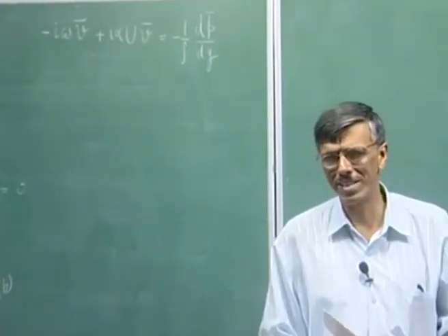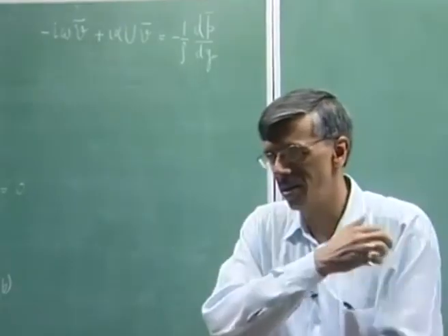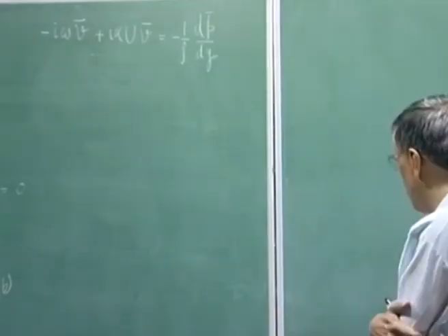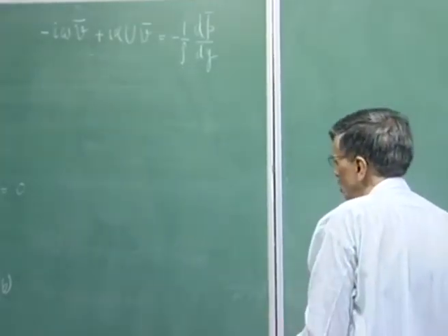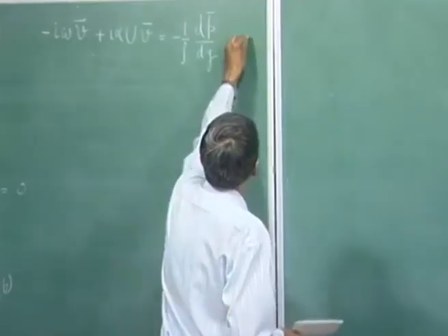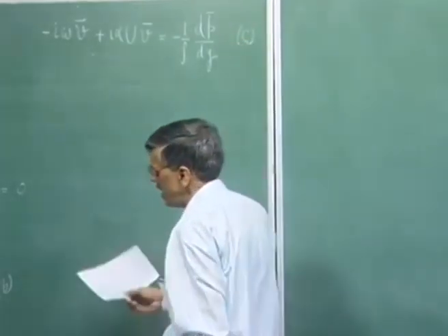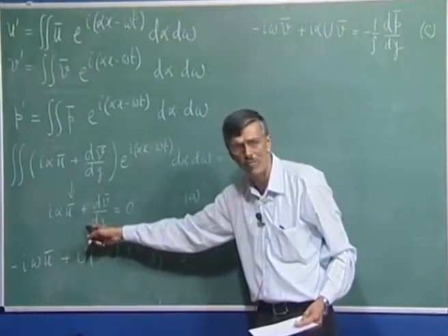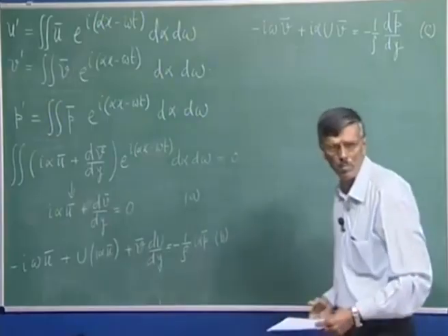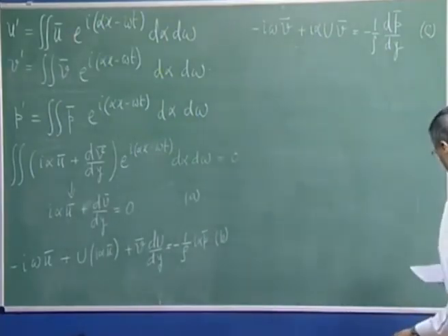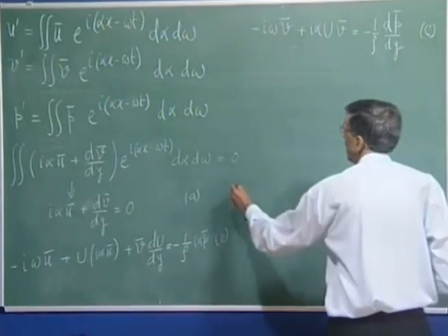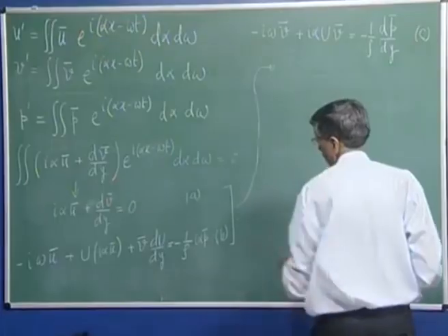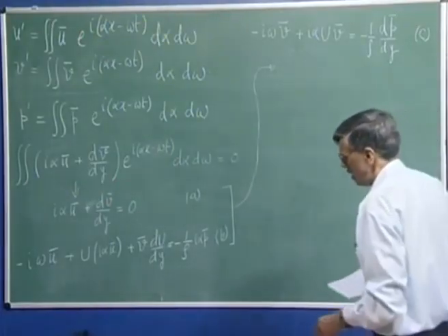Right? So I have basically 3 equations for these 3 Fourier Laplace amplitudes, u bar, v bar, and p bar. Now I could use this equation A, and I can see that u bar is nothing but minus of 1 over I alpha dV bar dy, right? So I could actually put these two together, and I have two terms there.